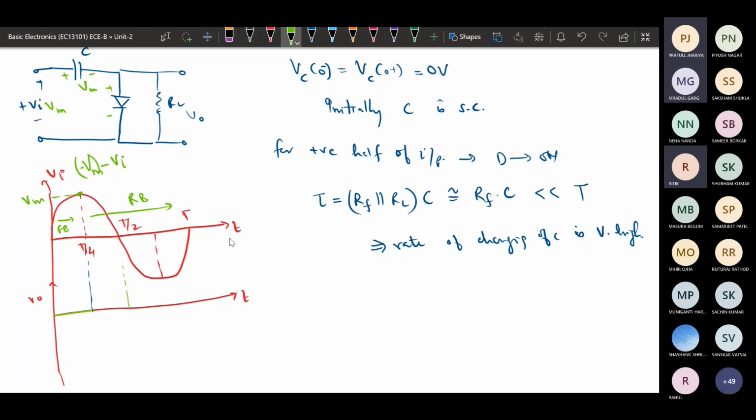So it is negatively connected and will always be, even if we reduce the voltage below Vm. Whatever voltage we reduce to, the diode will always be in the reverse bias case. So it is an open circuit now. If it is reverse bias, it is an open circuit. So the output voltage is whatever the input voltage is with respect to plus Vm. So the output will be the same waveform as the input.